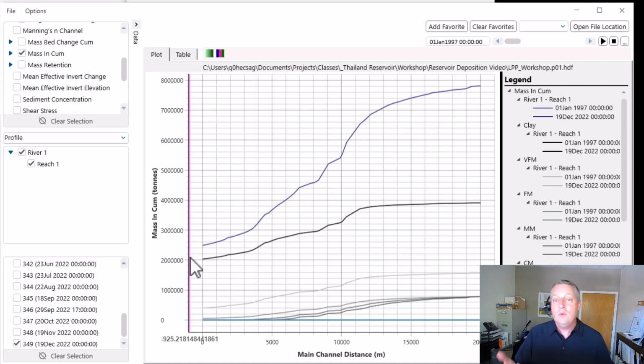And so if you need more trap efficiency, if you feel like you're passing too much sediment, let's say your downstream concentration results are too high compared to observations, then you can move material from your fine silt and clay grain classes and assume, oh, actually there's more flocculation going on than I thought, or the vertical mixing bias is stronger than I thought, and you can move those into the coarser grain classes. And so that's just a very brief primer on a very simple reservoir model.